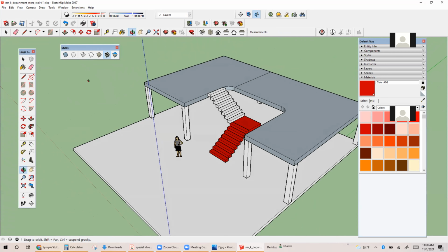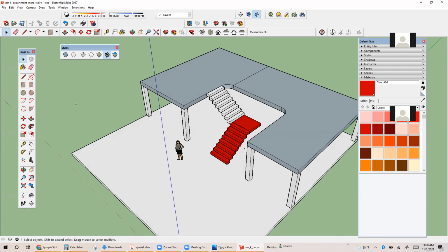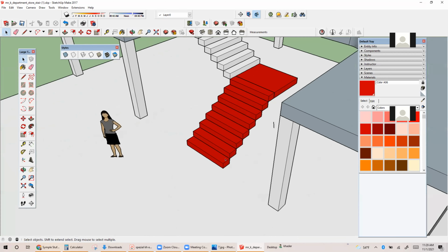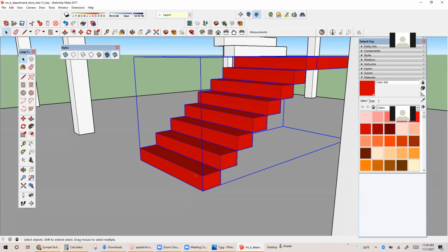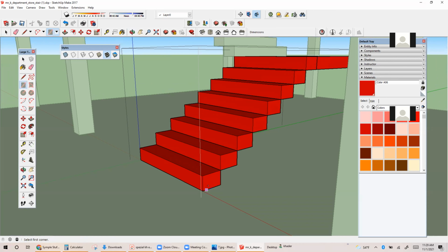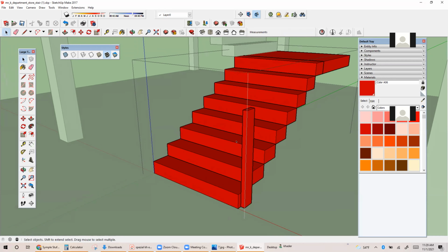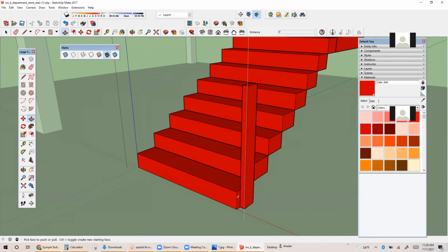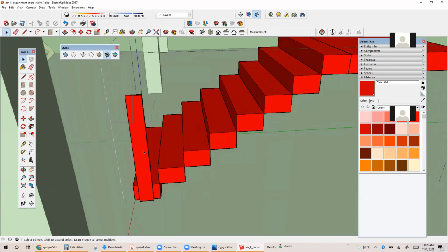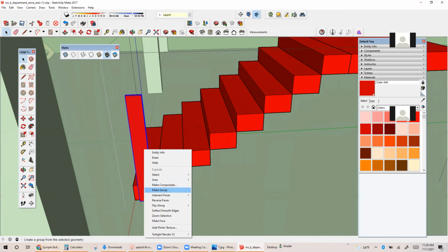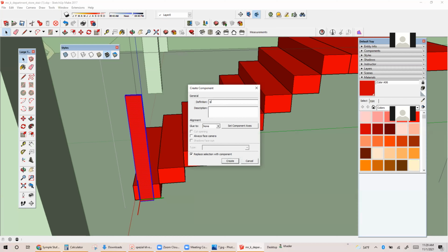Yeah. Second thing would be to make railings. And you remember we made railings before, so I want to make modern railings on the stair. So I want to make maybe glass pieces that attach to the side and go up, let's say 40 inches. Remember, this piece is not part of the component yet, right? So I will highlight this, make it a component, call it glass railing.